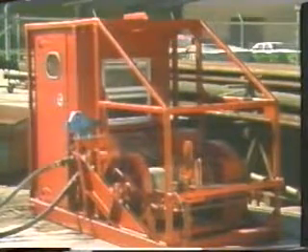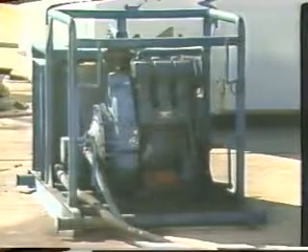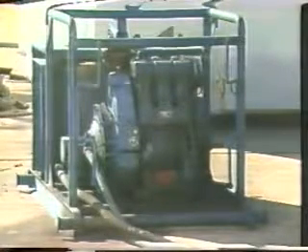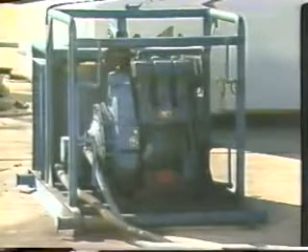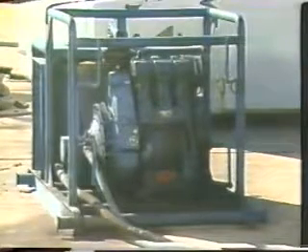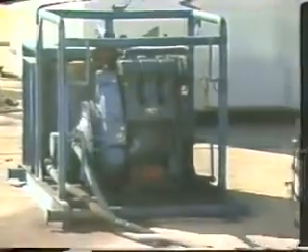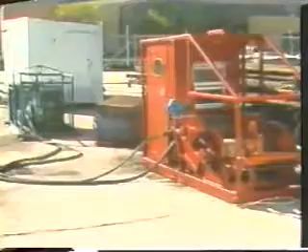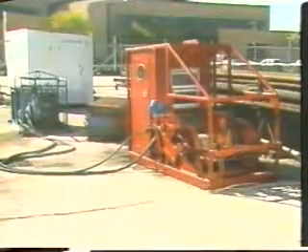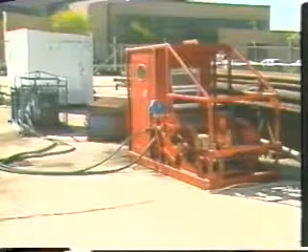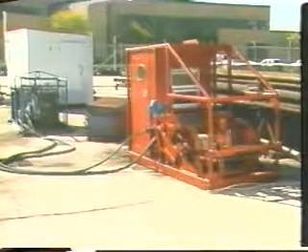The reel systems used on wireline units must have a power supply, which may be a diesel or gasoline engine, or an electric motor. This power supply may run the reel directly, or else operate a pump to supply fluid to a hydraulic motor. Most modern wireline units use hydraulically operated reel systems, which gives the wireline specialist the precise control needed to perform sensitive wireline operations.